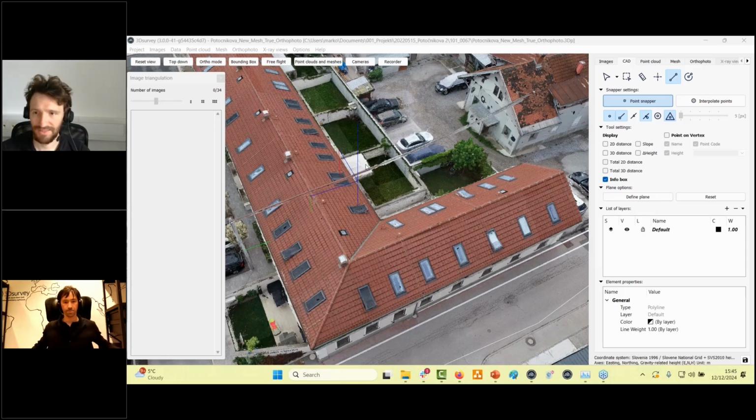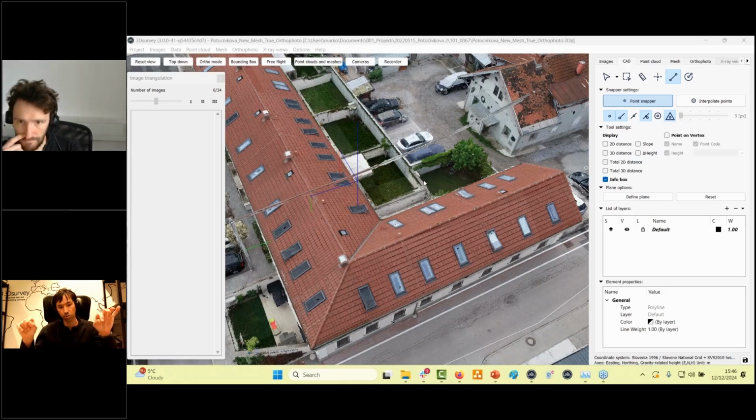We have only three more questions and then we're done. Is it possible to georeference LiDAR point clouds in 3Dsurvey using ground control points? Yes, it's possible. You just use the manual registration approach. You need to have a scan model for this, and you show points on a point cloud and show which point you would like to attach. You need at least three of them, and that's it.